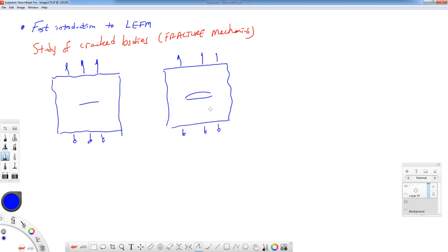And the idea then is that at this surface between the top surface and the bottom surface of this crack, we are not transmitting any stress. We don't have any tractions that go through that top and bottom surface anywhere along that crack front. And in fact, for the Westergaard solution, this was the basic idea, is that those surfaces needed to be traction free for stresses in the vertical direction and for stresses that are shear. Okay, so these go to 0 at that crack face.